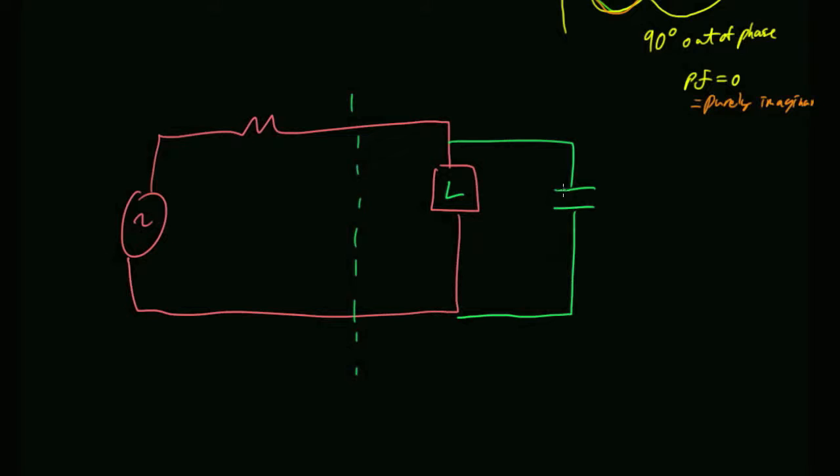So there's a calculation in the book where they basically figure out exactly how big of a capacitor you need to increase your power factor. Okay, but essentially what you're doing is figuring out how much power is being thrown back onto the line, and you're putting a cap there to say, hey, instead of throwing that current back onto the line, throw it into me. I don't care. I'm just sitting here, right? I like taking extra power. So you size this thing so that when there's power to be thrown off by the load, instead of being thrown off into the line, you throw it back into this capacitor. Okay, and thereby it's more efficient. You don't waste your power in the line.